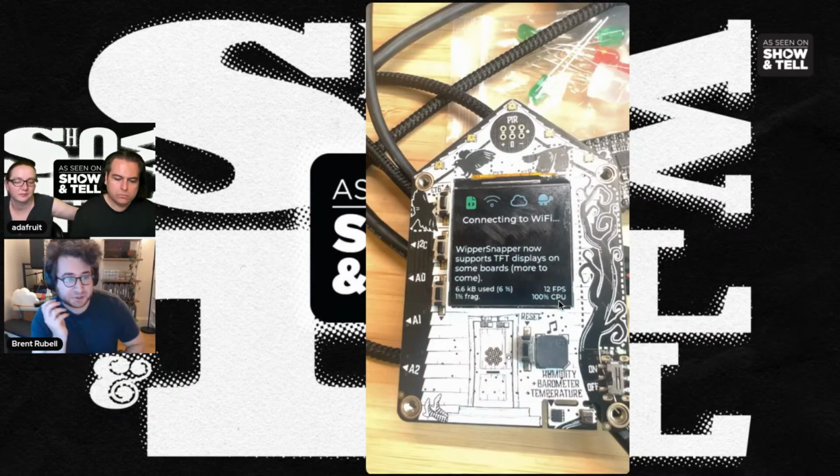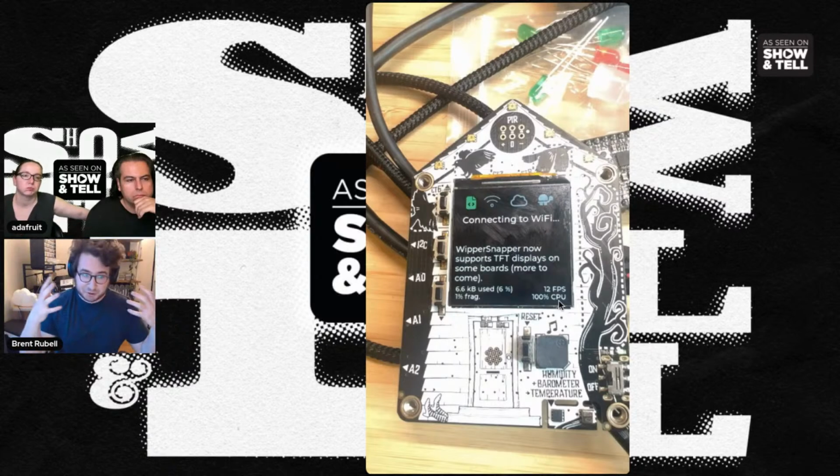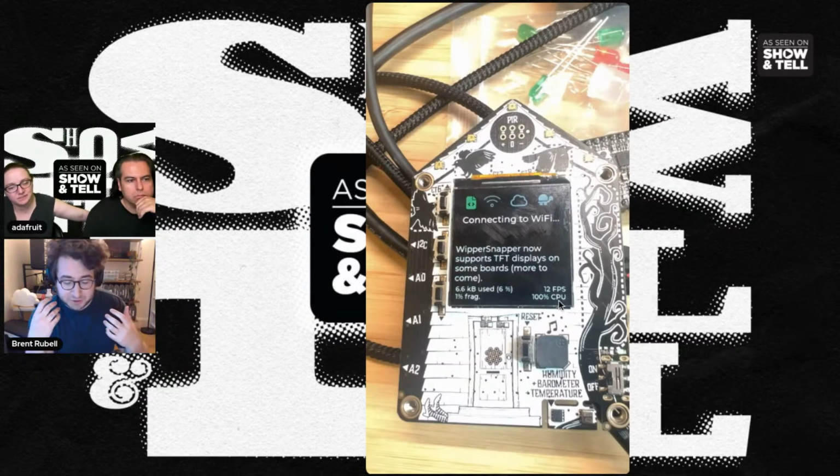That was starting to hit me last month, and I worked around it with Phil B, who came up with this library called LVGL glue. So all of the Adafruit displays can use LVGL in a really easy to use way, and Phil B, Paint Your Dragon, developed it. I was working with him on getting around this issue, because every single time you do a project and you bring in the overhead of Wi-Fi, or the overhead of display and Wi-Fi and NeoPixels, you're really starting to constrict what you can actually do.